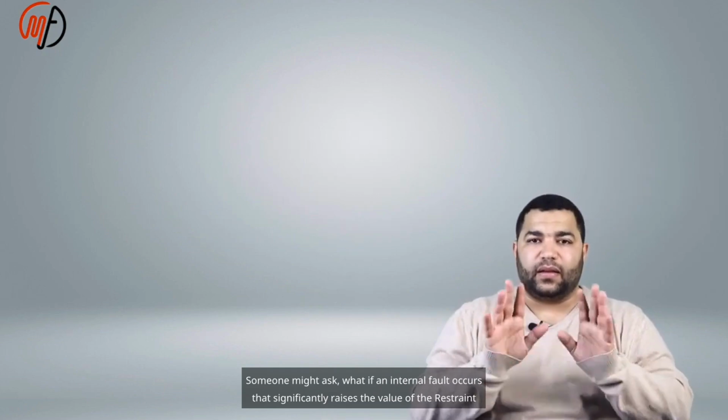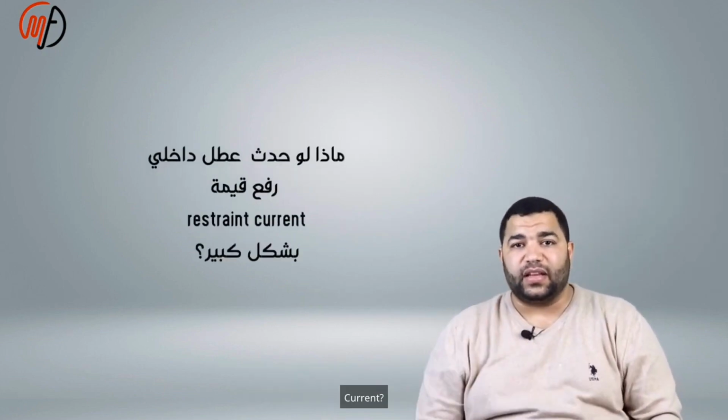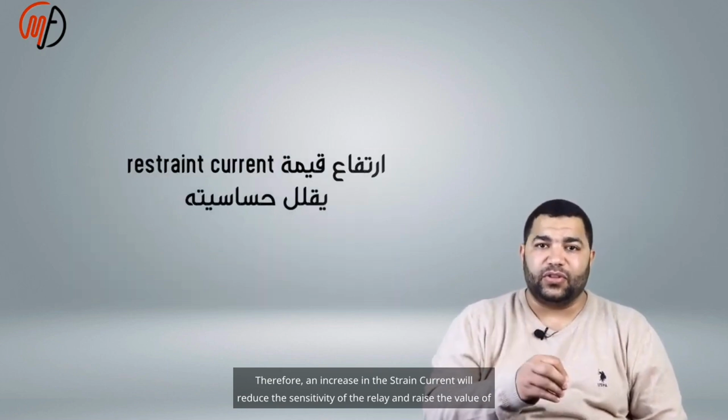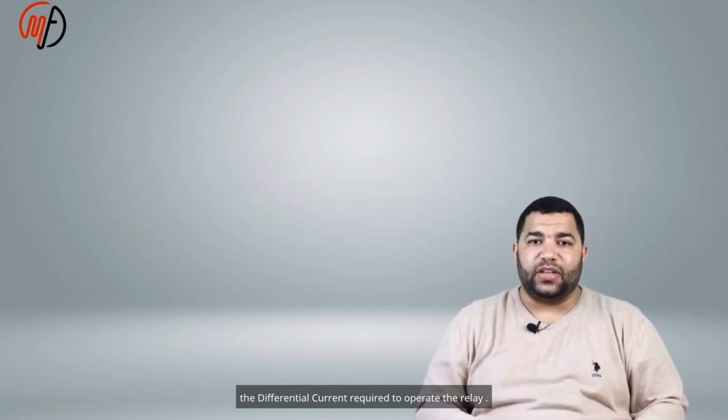Someone might ask, what if an internal fault occurs that significantly raises the value of the restraint current? An increase in the restraint current will reduce the sensitivity of the relay and raise the value of the differential current required to operate the relay.